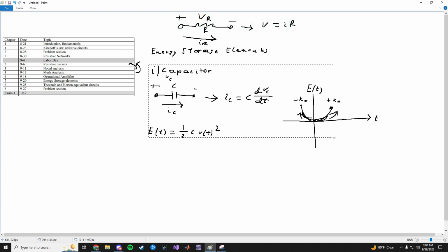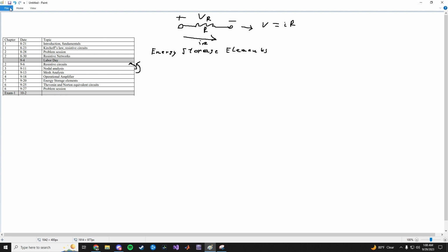And so next would be the inductor. Remember earlier how I mentioned dual concepts. So that's going to be the capacitor, which is C dVc over dt equals I. Well, for an inductor, let's see what the equation looks like. For an inductor, also a two-terminal component, this would be VL, the constant inductance is L, and the current through it is IL.